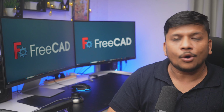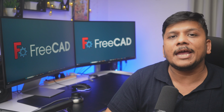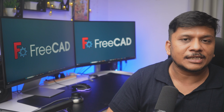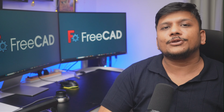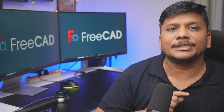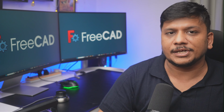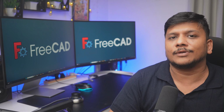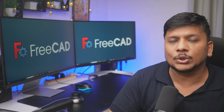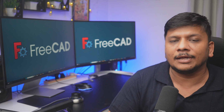That's why all these engineering software are known as parametric, because everything in the sketch is controlled by a certain parameter that we define. Now, when we talk about FreeCAD, you're going to see a length constraint, which locks or constrains your length. Then there is an angle constraint that you can utilize to control the angle between, let's say, two line segments. Then there is a radius constraint, diameter constraint, and lock point.